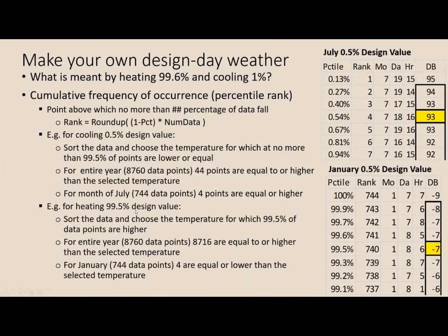So if you decide in the end that the design day data is just not sufficient, what I did for some projects was create my own design day weather. I ran a dummy model to generate text files with all the hourly weather data, and then I imported them into a workbook and sorted them and calculated all kinds of things to get the design day weather.